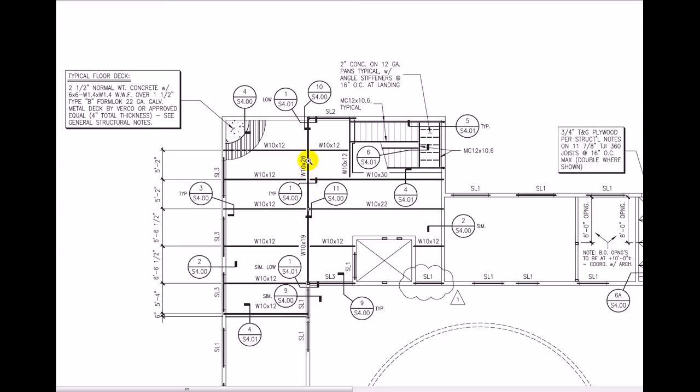We can see which beams support which beams by the gaps. So for instance, the first thing they would build is the column. Then this 10 by 26 would come in. They'd build the exterior wall, and then the 10 by 12s would frame across. So the gaps indicate where the different beams end.